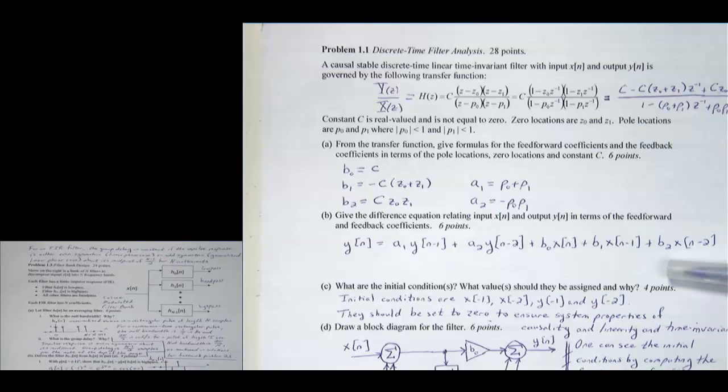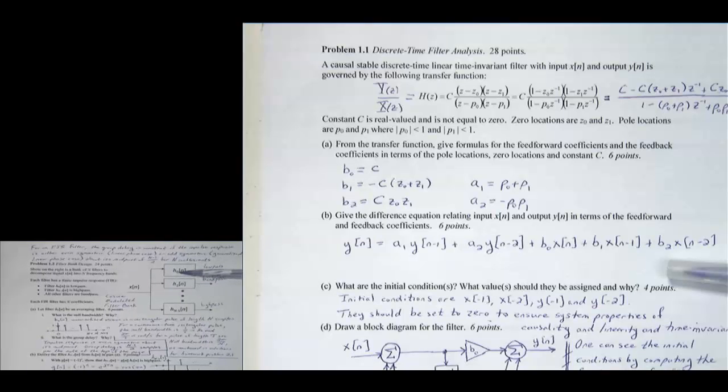And each filter has n coefficients. So when n is 2, this reduces to 2-tap averaging, 2-tap difference, or first-order difference and 2-tap averaging, normalized if you want to. You don't have to normalize. So 2 channels, 2 coefficients. If I have 3 channels, each filter will have 3 coefficients, and so forth.